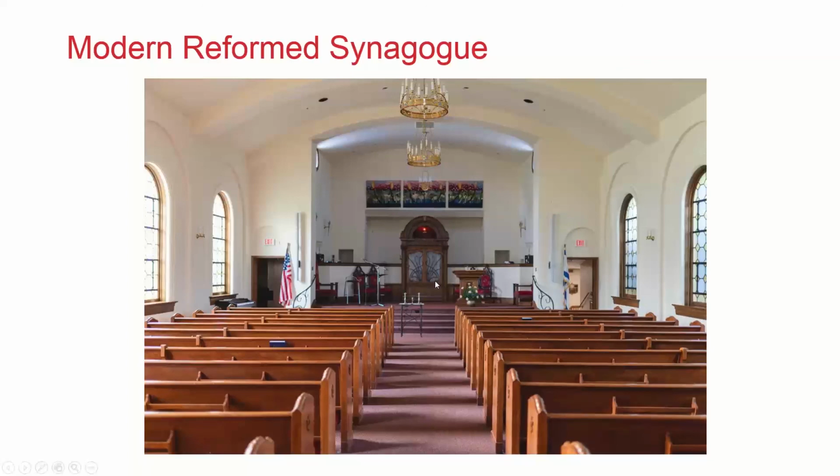In a room like this, you don't want to put anything audio in the center line of the room. Don't put the console, don't put the microphone, don't put the speaker, because of that focusing. And if the sound source is over here, it's going to bounce back and come back, a double hop back.